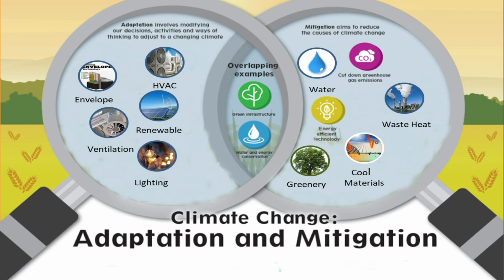We have all possible studies. We know the real potential. Is it enough to apply these technologies? No. Why? Because the magnitude of the overheating is much higher. We have capacity to decrease temperature up to 4 degrees. Unfortunately, overheating is more than 5, 6, 7, 8, 9 degrees. So what do we have to do? We have to combine adaptation and mitigation. Adaptation means better buildings. We cannot continue with this quality of the buildings. We need to have buildings with much better thermal quality.